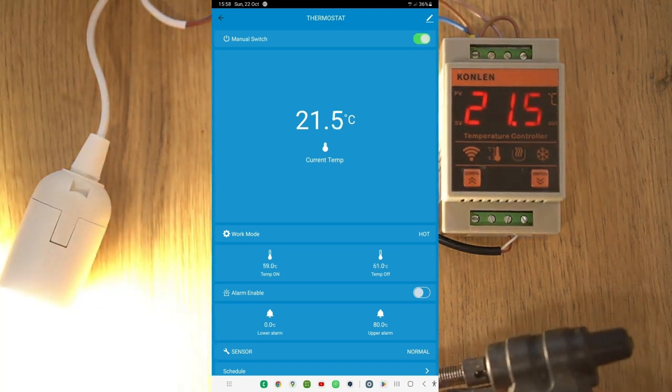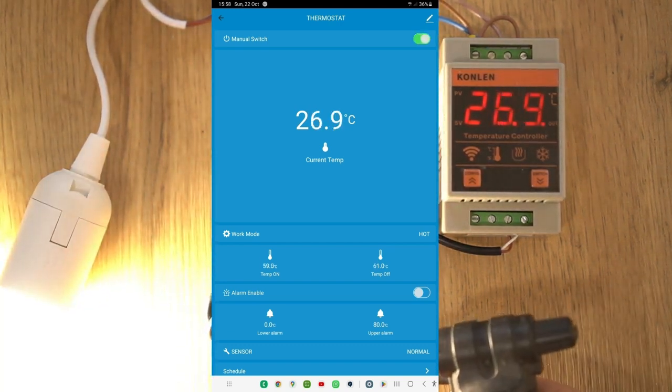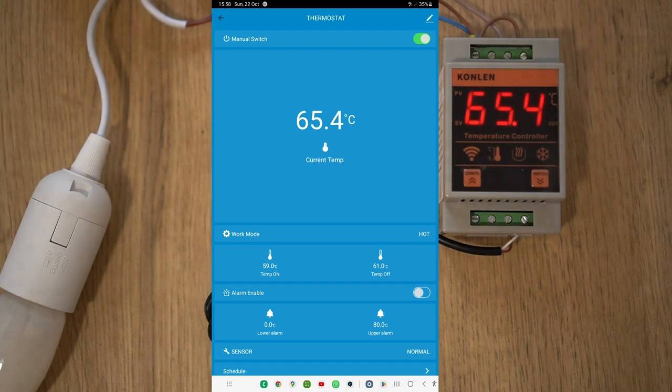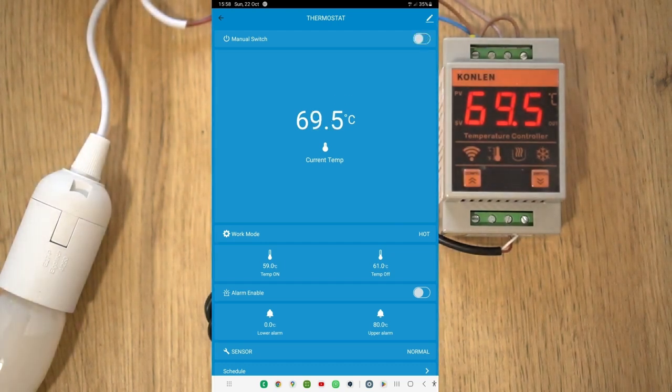Continue adding as many time points as required to our daily scene, changing the parameters to suit your needs. This process allows you to create an infinite number of points to control the boiler each day. I don't know if there is a limit to the number of time points per scene, but you can easily add 10. In each time point, you can set your own temperature parameters for switching the boiler on and off.